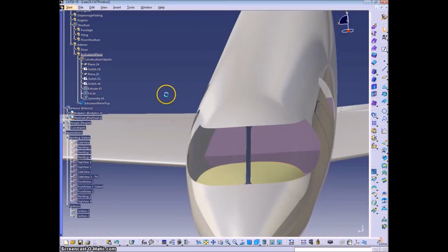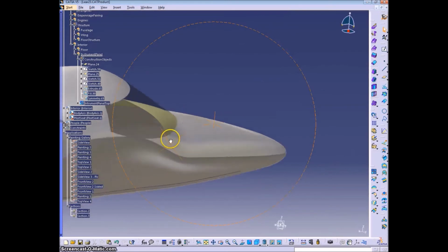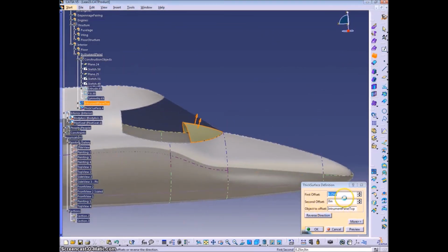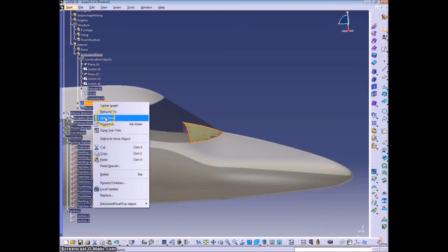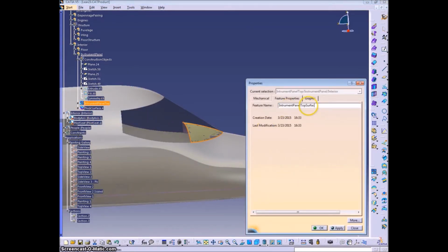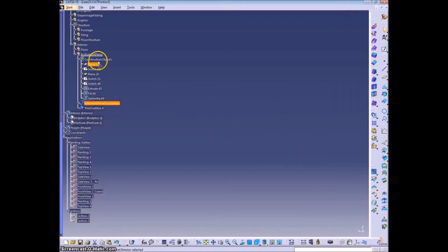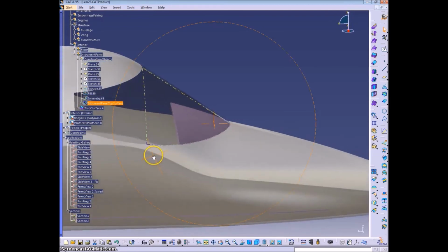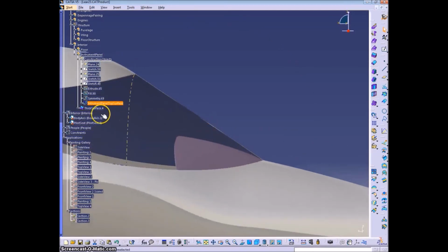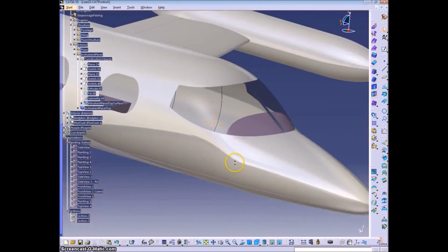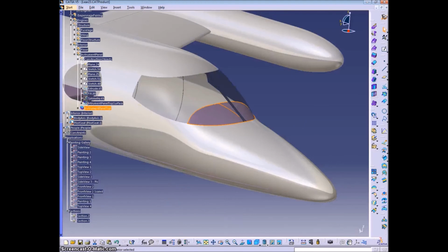And we're going to make this surface into a solid by creating a fixed surface, which is that squiggly button, the purple one, purple and teal. And I just made a thick surface in the opposite direction, or in the down direction, so to speak, so as not to go through the window. You can choose whatever thickness seems appropriate to you.